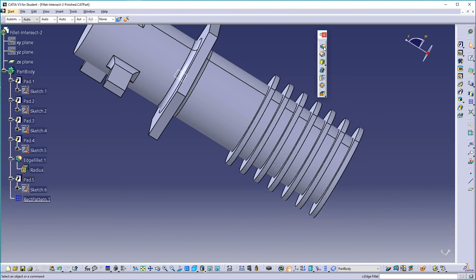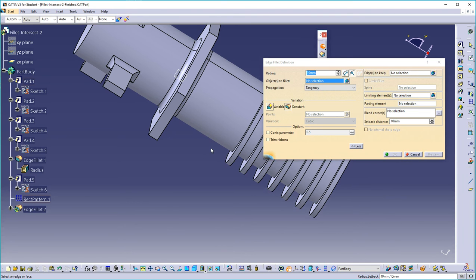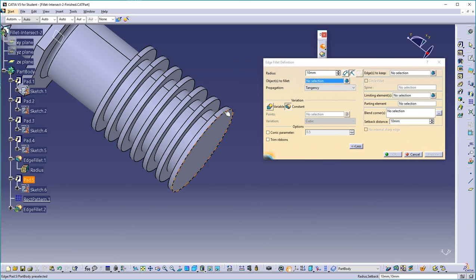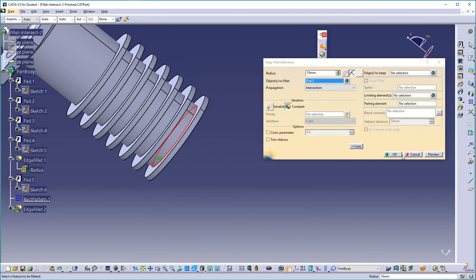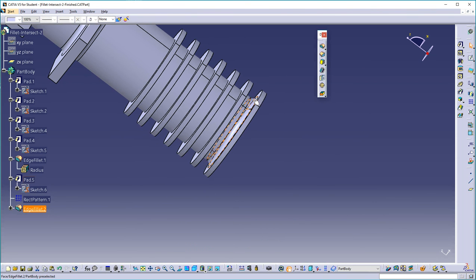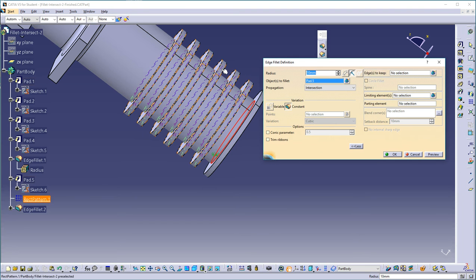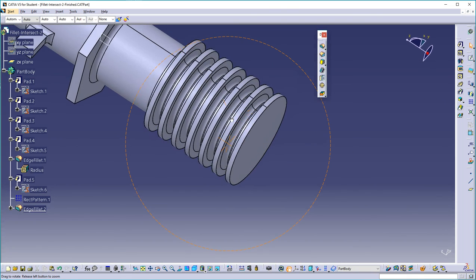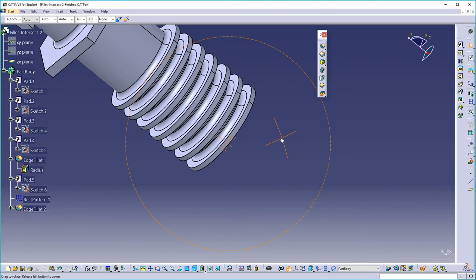So now let's select the fillet icon, and let's pick this pad as the object that I would like to intersect with the current solid, and it found that edge right there, and we'll say OK. And that's great. Now let's double click that. I wonder if we can add a pattern into the group. So let's select it, and sure enough it did. And what an easy way to add fillets to this entire group. Okay?